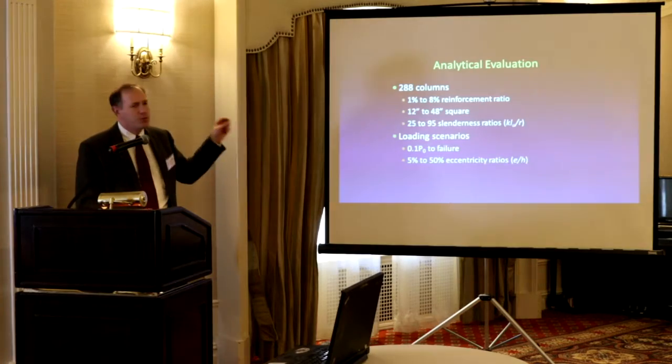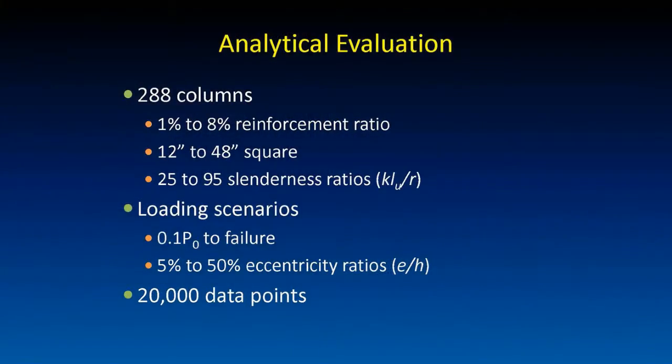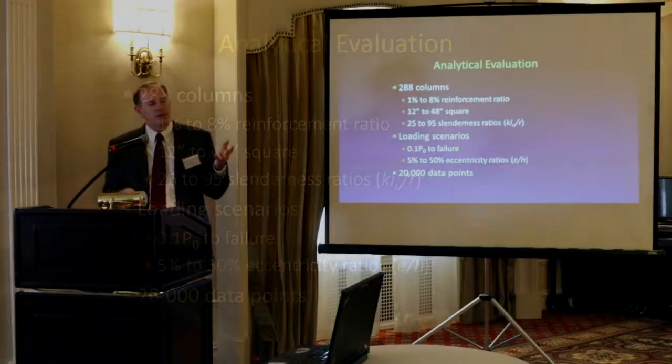We had load scenarios. We started at 0.1 of the axial at P0, the actual capacity of the column, and took it all the way up to failure. We also looked at eccentricities all the way from 5 to 50%. 50%, I think, is a beam. I mean, it's huge eccentricity. This was 20,000 data points. We ran 20,000 essentially columns and simulated those tests.